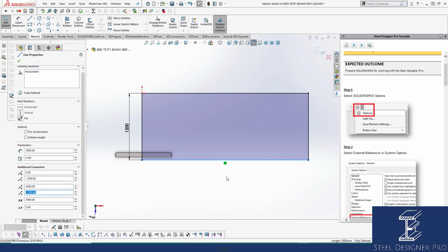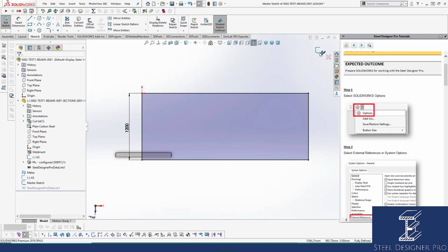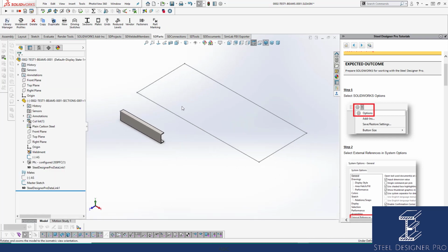So when you're looking at a sketch in 2D, it's X and Y only. So X is obviously from left to right, and Y is up and down. So in this particular case, you can see that the Y values are identical, and you can see that the lesser of the two X's is the start point. So that's definitely on origin. So we know that this is the start point, and we know that that's the end point. Exit out of the sketch.